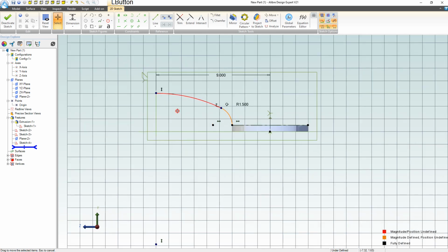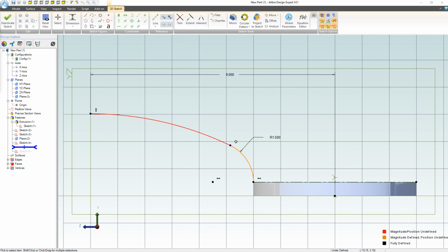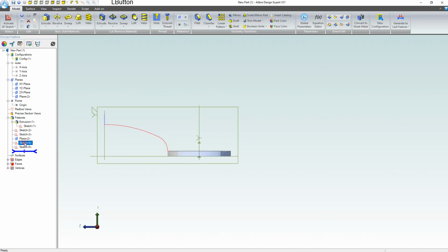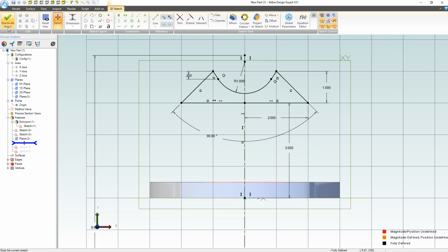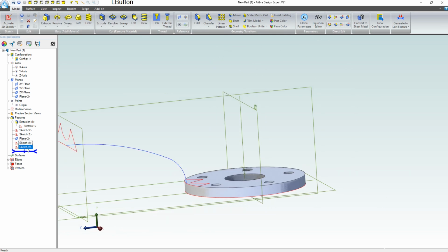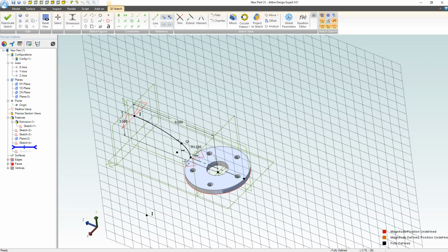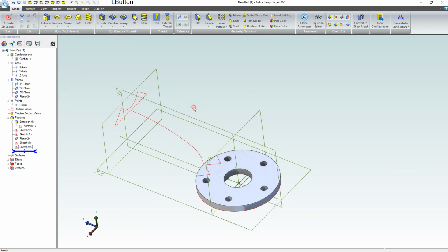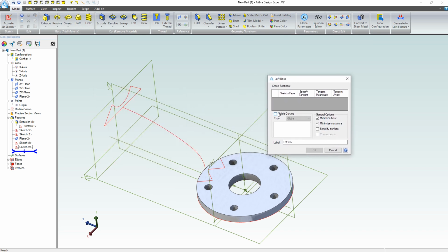And it's how high is that point? That should be pretty easy to find out because I did something in sketch 4 earlier, so 3 inches from the origin. That is nice and simple. We'll head on back to sketch 5, edit, and we'll add in a dimension. So we know that we start at the bottom of here and go to the bottom of here, and hopefully that'll be kind of a cool profile. This is telling me that my sketch is not closed. I'm going to ignore that warning, and I think it will be acceptable as long as, you know, I'm using a guide curve. So let's choose this loft feature here. Maybe I can choose this in the GUI.